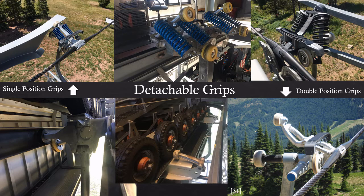Grips can either be in the open position, where the jaws are larger than the diameter of the haul rope, or in the closed position, where the jaw is the exact diameter of the haul rope so that it can be attached. Single position grips have one default setting, where the grip is closed. The grip will only be open during the period where the carrier is detaching or reattaching to the haul rope. Double position grips have two default positions. The grips can be closed when they are on the haul rope, and when they are traveling around the terminals, they stay in the open position.